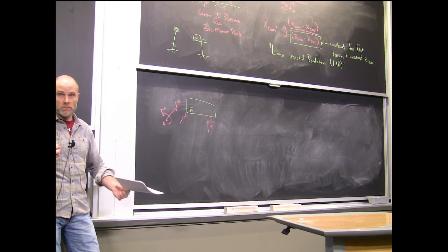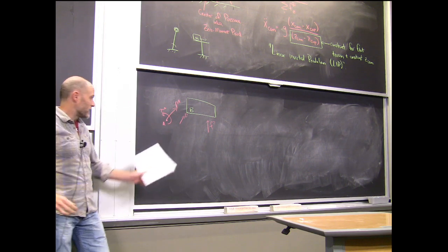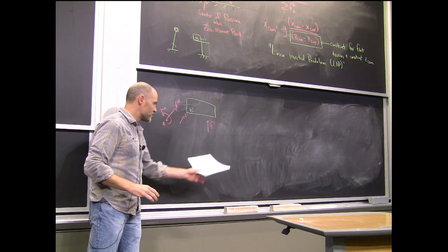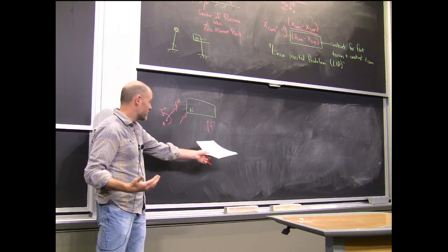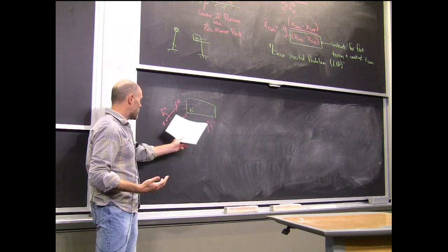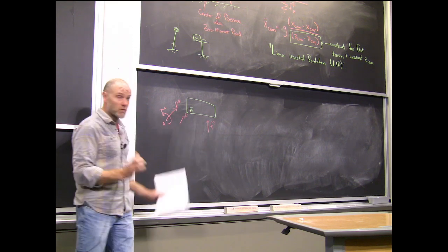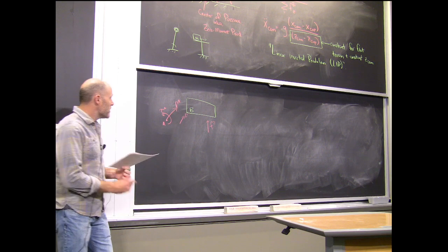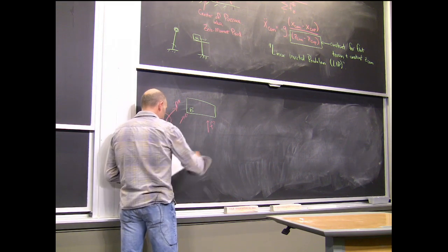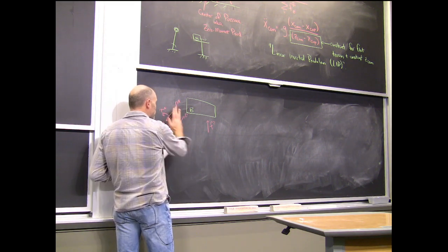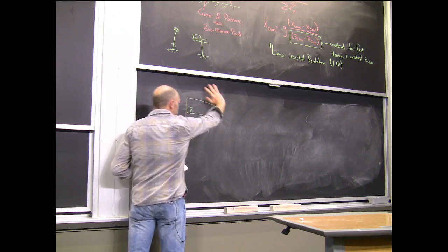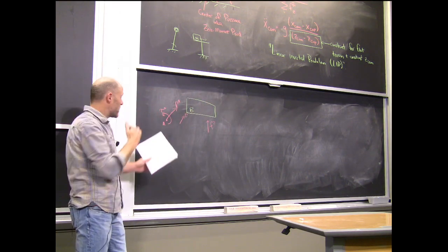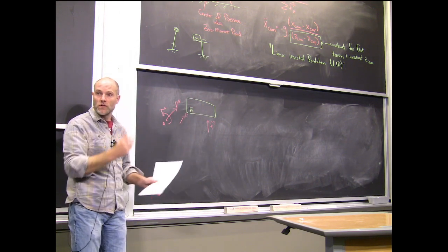That's just rigid body mechanics: forces add in the multi-body equations, and I can summarize them all as a force and a moment at a point. If you choose to put that summary in different places in space, then the force component will shift and the torque component will shift.